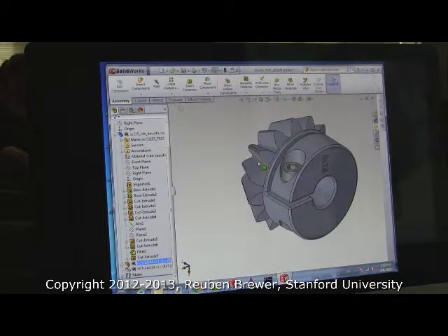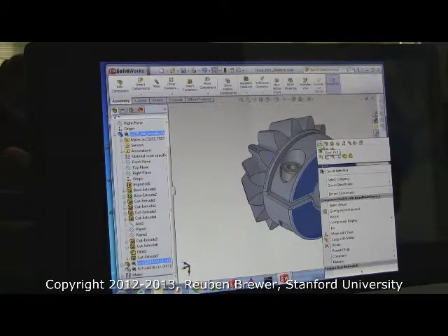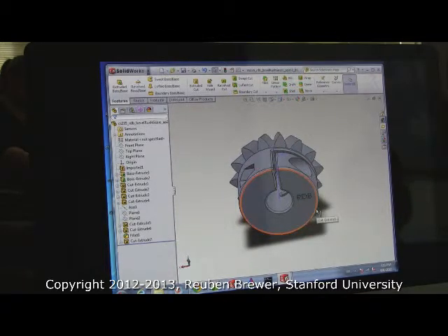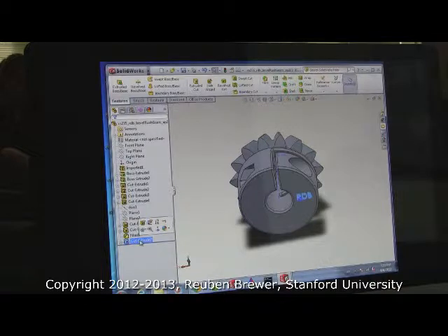This is usable as this is one of the assemblies in your homework. So go ahead and open this gear again. Say you have part of the gear that you don't like and you want to get rid of it. Let's select your initials. You're tired of it. You don't want to delete it because maybe you'll put it back later, but you just want it to go away. You don't want to hide it because it's still there. See this button here? Suppress. Click that. It goes away. It's still there, it's just grayed out. We didn't delete it. Now click it again and unsuppress.